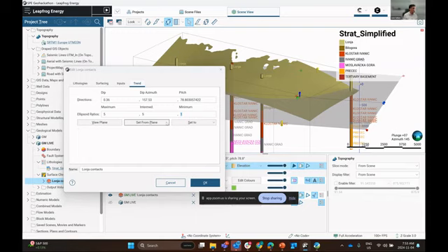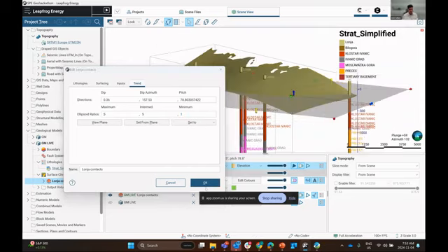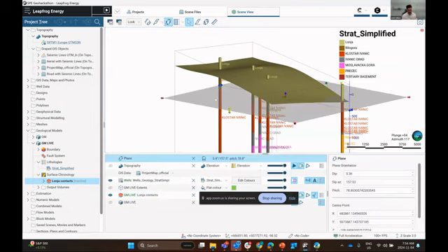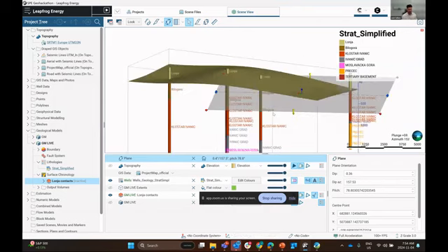All surfaces that you build within Leapfrog are by default isotropic, which means that the ellipsoid ratios for a surface that you're going to build is by default stretched 1, 1, 1. Especially in areas where you have stratigraphic sequences, you may want to apply a trend to flatten this out in a particular direction. So this is where you can apply some anisotropy to do exactly that. So we can apply these ellipsoid ratios and we can essentially flatten this surface out. So this stretches this surface in the direction of that plane.